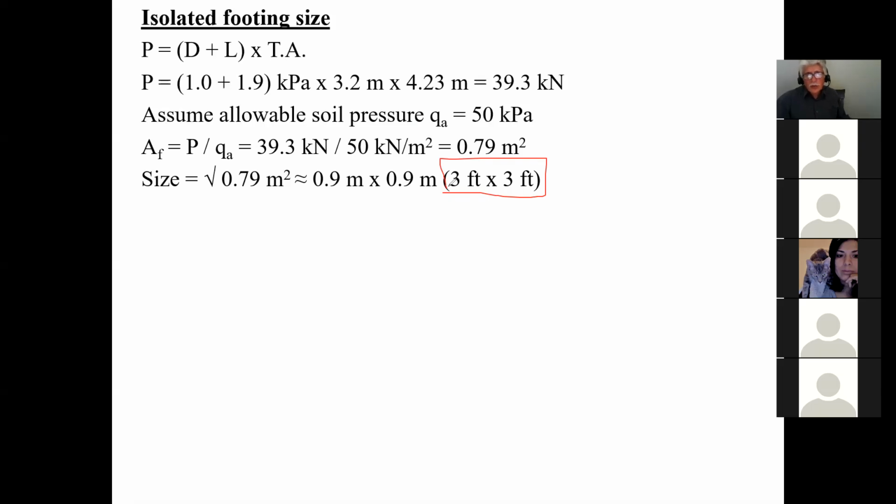Like I showed you, in certain cases a plain footing is as advantageous as a reinforced one. In one of the assignments I showed you, I took such a light load that the plain footing ended up being about the same size as a reinforced one. Understand? So it's up to you, but that's something that you do in concrete. So if you guys can dig up your concrete notes, and if you had to do this in real life, that would be an additional calculation you'd have to do for this project. Understand?